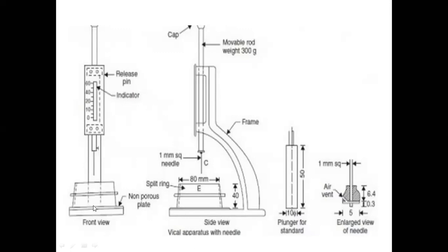First, if you add 24%, it will automatically be very hard, so the penetration will be very low, because it will be very hard. The penetration is going to be very slow, and we may get a reading of more than 7 mm, when the required range is 5 to 7 mm. We told you 5 to 7 mm, but it may even be 10 mm from the bottom.